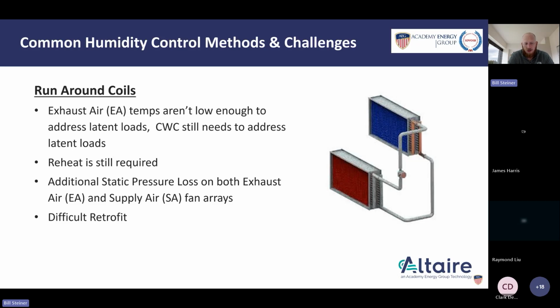So if you're employing this as pre-cooling, preheating, that's great. You're going to get some energy recovery, but you're still going to have to subcool all of your air volume, or have a secondary means of subcooling just your outside airstream if you choose to decouple, because this won't get you down to the dew points that you need to get to.